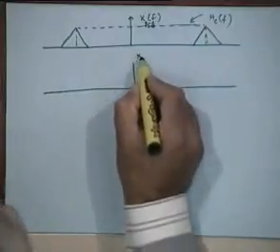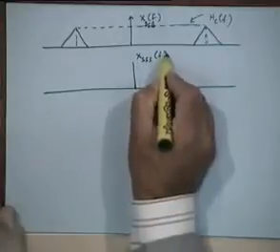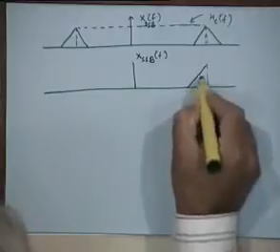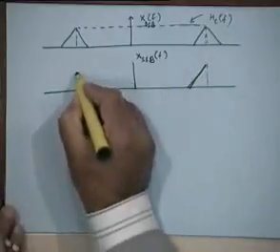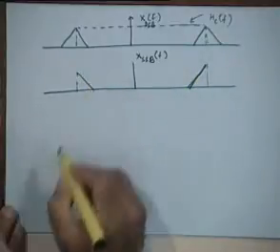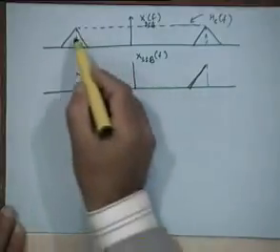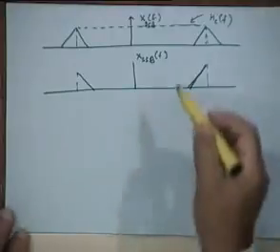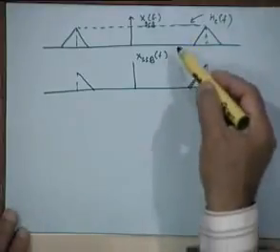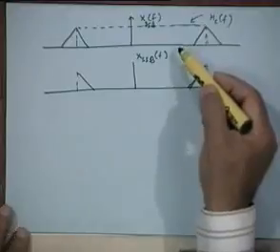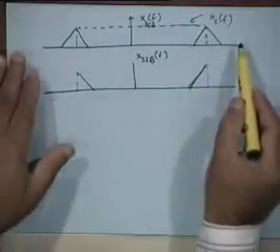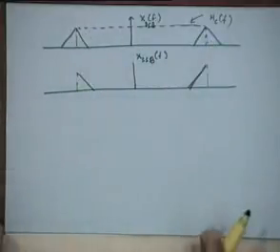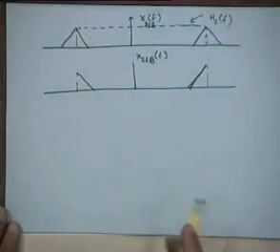The corresponding X SSB spectrum would therefore look like this, after this low pass filtering. So this is the process through which the SSB waveform is generated in the frequency domain: multiplication of the DSB-SC spectrum with the transfer function of this kind of an ideal low pass filter.